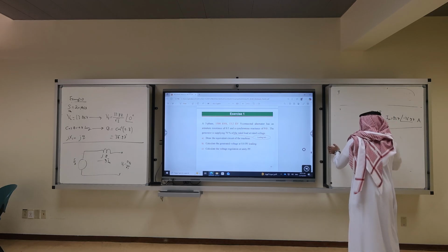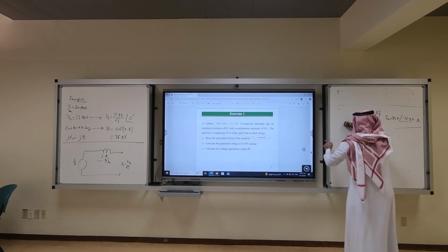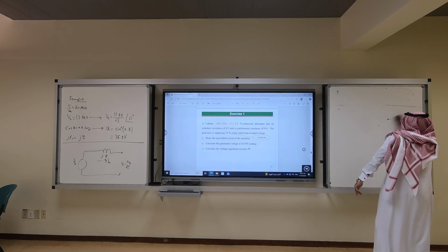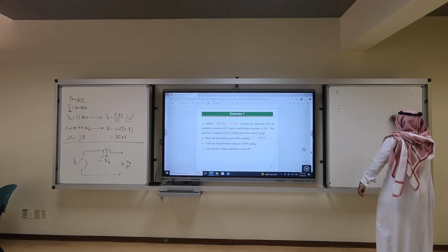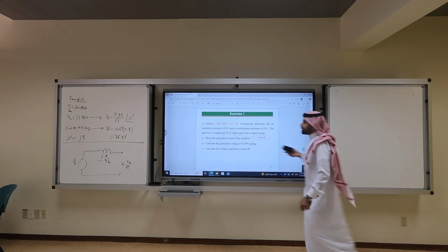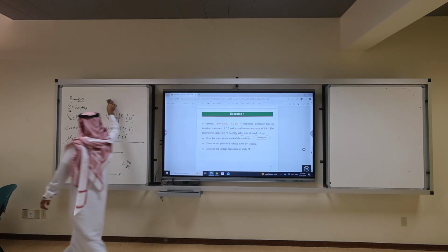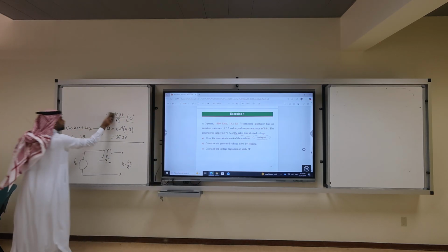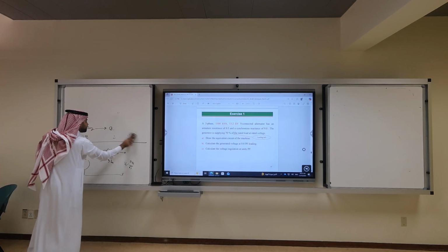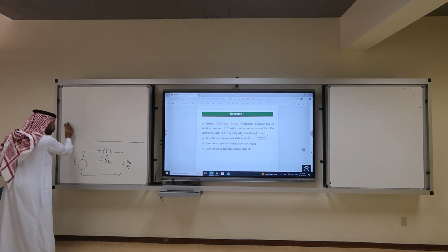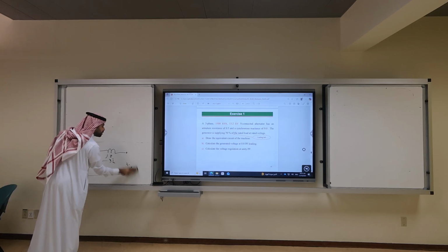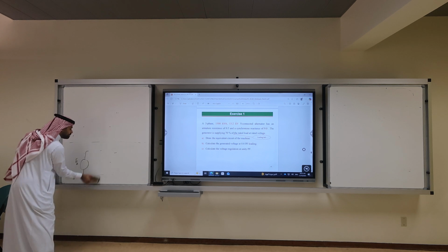Are we operating at rated condition? Look at this arrow. No, he's telling you the loading information is smaller. It's only 70%. What is 70% of 1.5? 1.05 MVA. So which one do I use to get an IA?